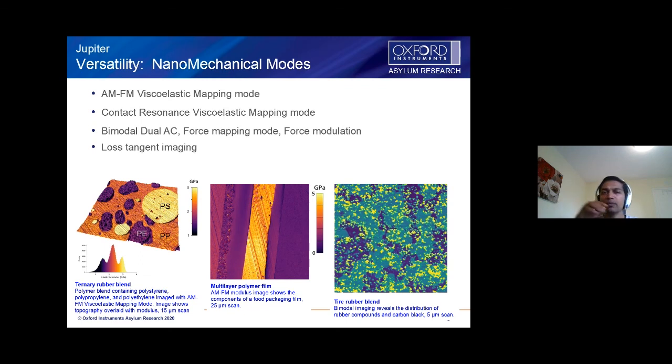And so this feedback loop gives you a more accurate or a quantitative measurement of surface charges. EFM is an open loop technique that gives you a map of the electric field. So the short answer is, if you can do KPFM, do KPFM. It is a more quantitative technique, but it is a little bit more complex to set up. EFM is easier to set up, but it is less quantitative.